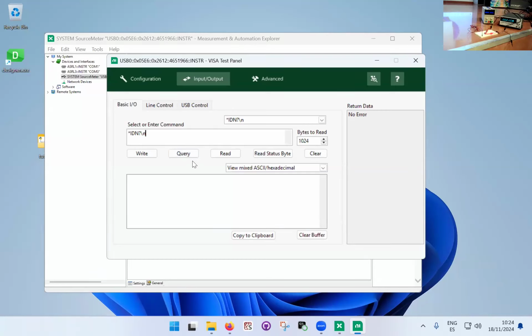There are many commands which you just send to the instrument to instruct it to do something, and nothing comes back at you because there's no need. And there's this particular syntax for this command, which is standard for all the VISA instruments, and you just need to know that it exists. It's in the manual, but you need to find it. It's this *IDN?, which means we're asking the instrument to identify itself, okay?